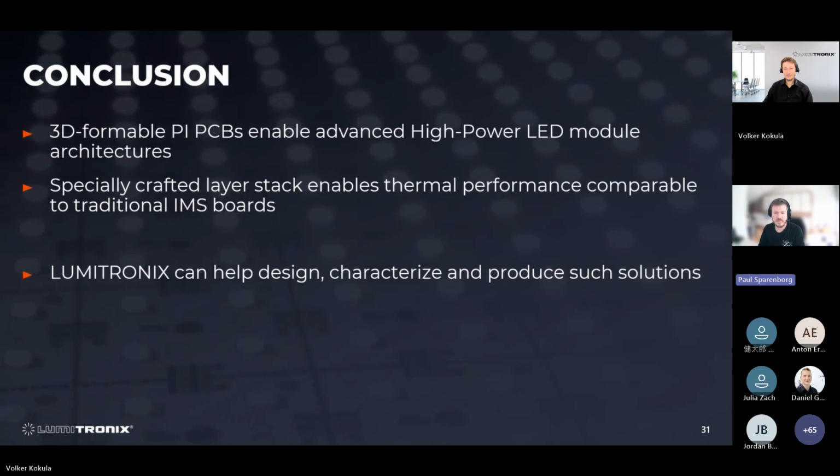So much less good thermal conductivity in the dielectricum, because it was using worse glue. It was using glue layers which added thermal resistance, which was not transparently visible in the datasheet at first glance.